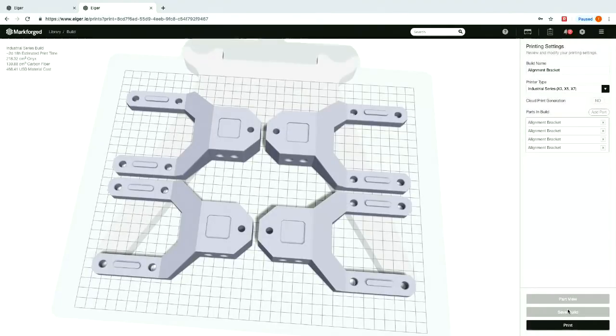Yeah, and I saw something else about automatic spacing. Yeah, right here. That's what I just did when I quickly added 4 parts. The answer again is sort of a yes here. We could be better about this, but if you add multiple of the same part, it will automatically space them. Personally, I would say this is not the most efficient because there's a lot of wasted gap space here. But you can do that. Our simple parts are very thin, like popsicle sticks. They're very small. You fit about 24 of them to a bed, so the way we create the builds is just adding 24 and it'll automatically do that for us.